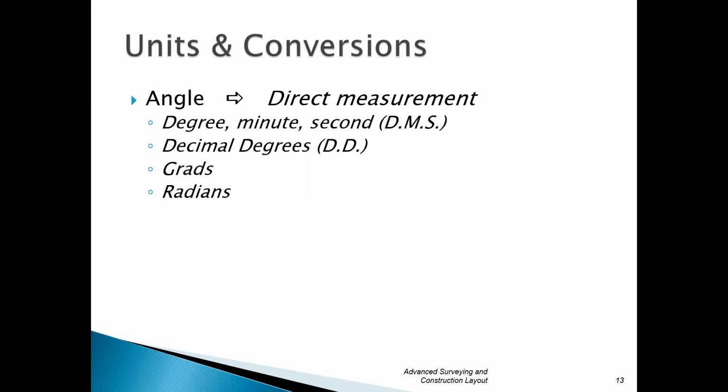So you won't see any surveying type instruments or layout type instruments. They're pretty much always going to be a degree minutes second format. However, if you're working with a calculator, a lot of times when you're calculating things, sine, cosine, tangent, those kind of things, your calculator may be giving you decimal degrees. So being able to convert back and forth between degree minutes second or decimal degree, that's going to be also something that'll be very important. Again, I'm going to show you some of these things as we get into this. On Thursday, we're going to go over this quite extensively.